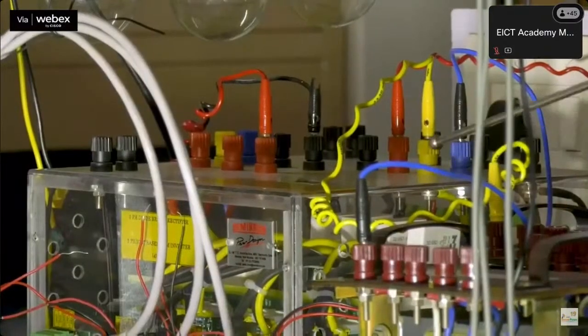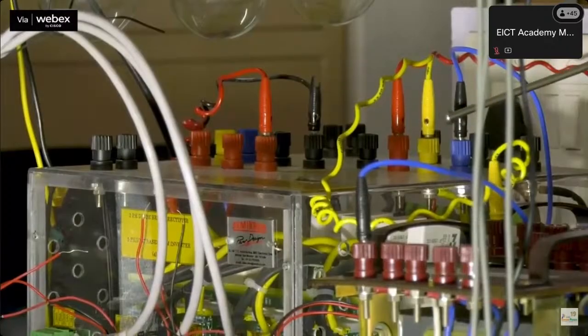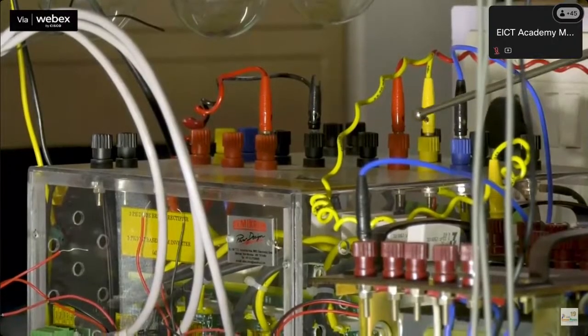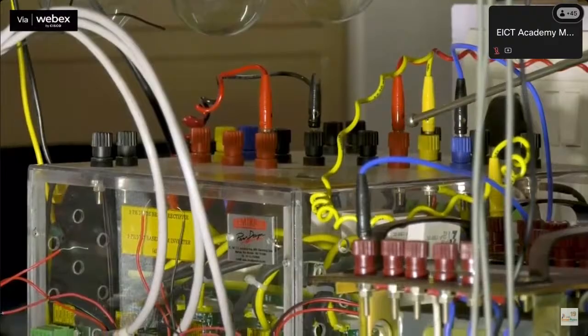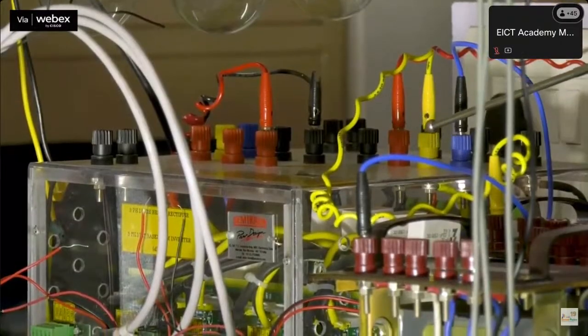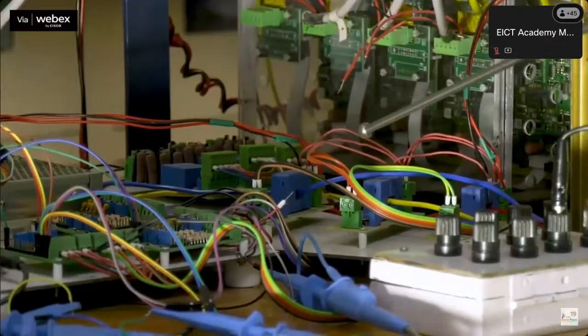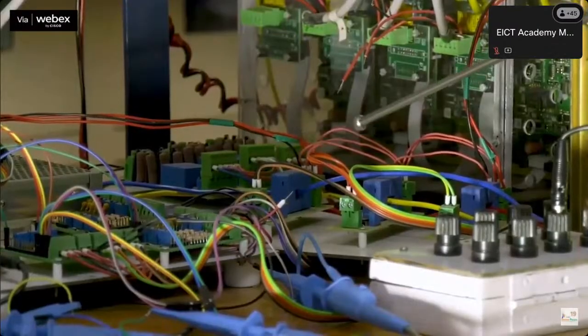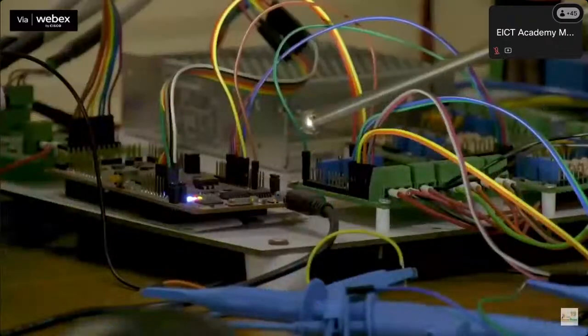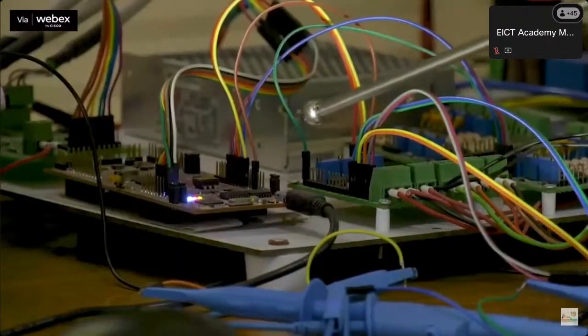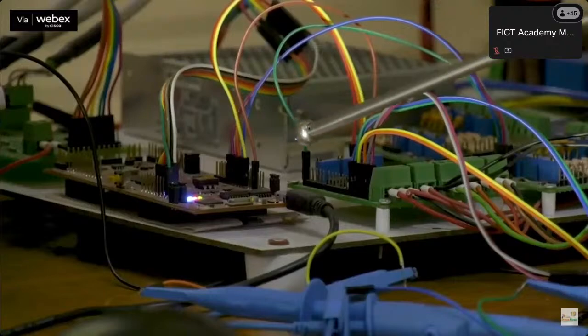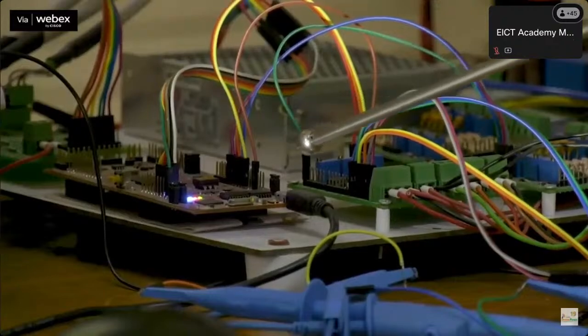The AC side of the Semikron converter stack is connected to the grid emulator through the filter with the help of a miniature circuit breaker, the so-called MCB. Voltage and current sensors are used to measure the voltage and currents of the AC bus and DC bus in the DC microgrid. The measurements are given to the DSP controller for processing and PWM pulse generation to control the converters. Let us discuss the hardware setup component-wise.